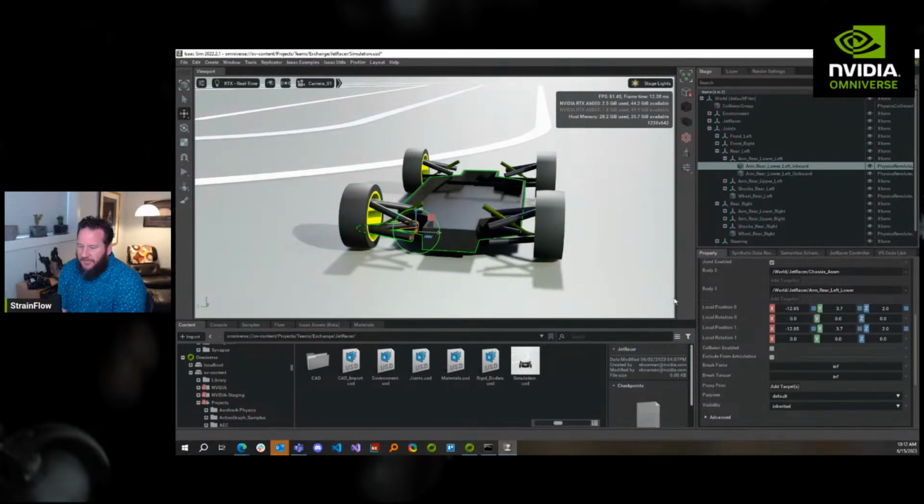The reason is that if you're working on a large assembly, in aerospace an assembly would have thousands of parts. Automotive too, right? If you look at Onshape, it has these really nice assembly constraints, which were great up to maybe 1,000 parts. But if you're constraining 30,000 parts together, forget about it. It doesn't work. It breaks. It's a mess. It's heavy. It takes forever to update.